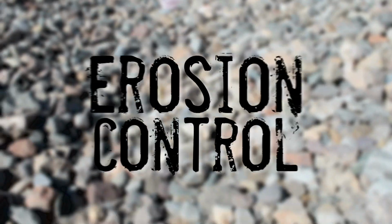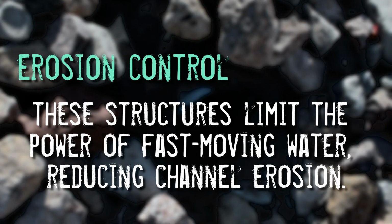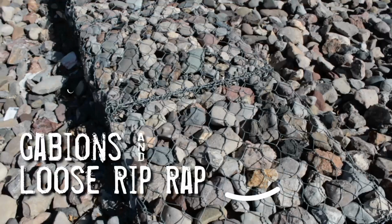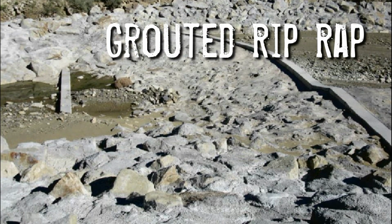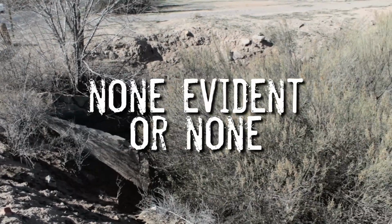It is time to talk about erosion control. These structures limit the power of fast-moving water, reducing channel erosion. Right here you can see a wire-enclosed riprap pad. Now some gabions and loose riprap, but in some cases you can find grouted riprap. If you are not able to find the erosion control, select Not Evident or None.